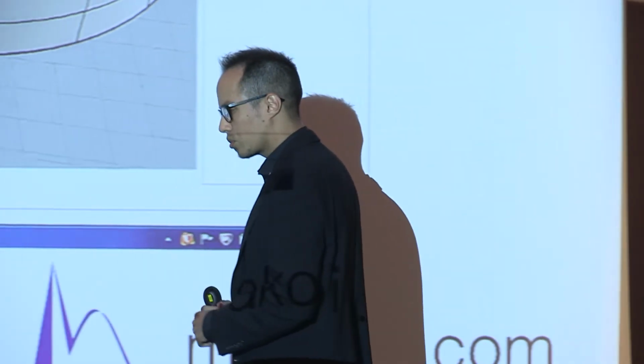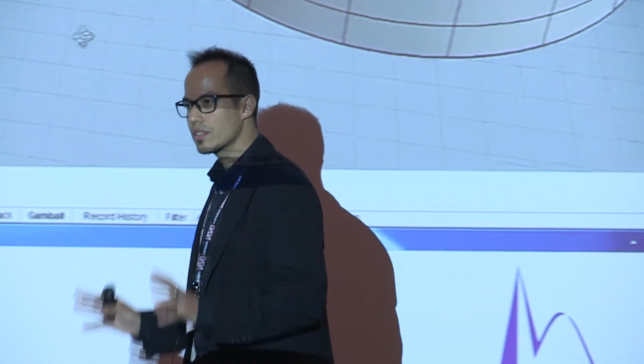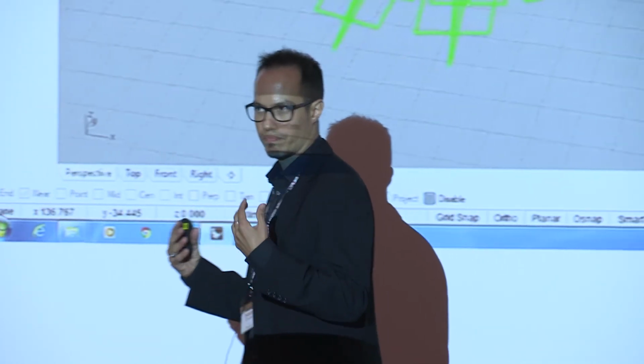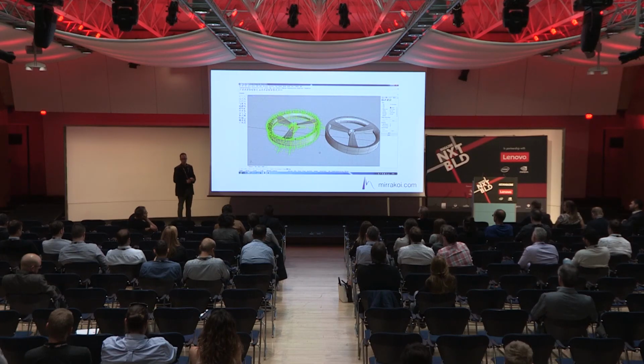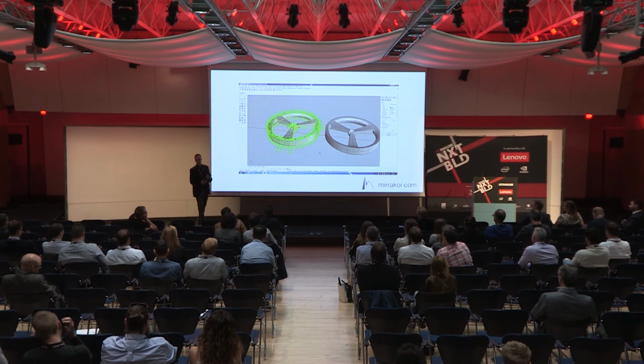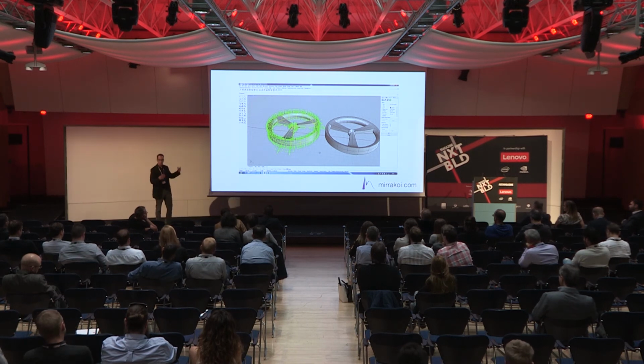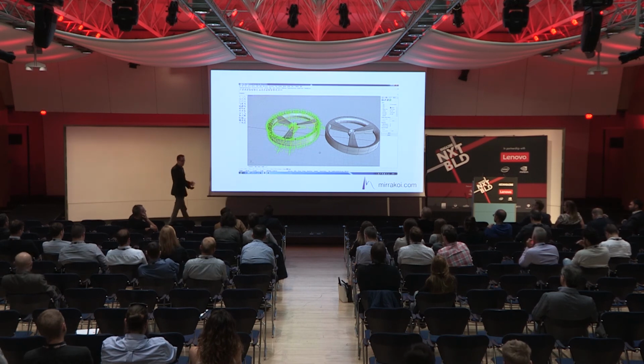Another thing that I want to highlight is that every single NURBS command or BREP command, if you know about the Rhino modeling workflow, is applicable to a Xyros object. So even if we don't specifically provide an operation yet, you can, for example, do trimming, offsetting, filleting, chamfer, all these kinds of things. Just apply any NURBS command to this object and it works.